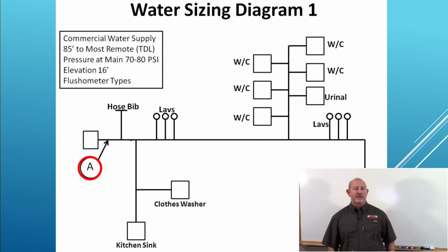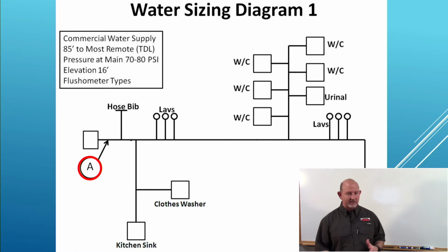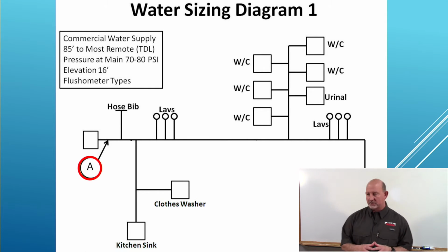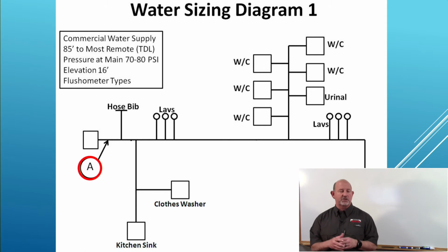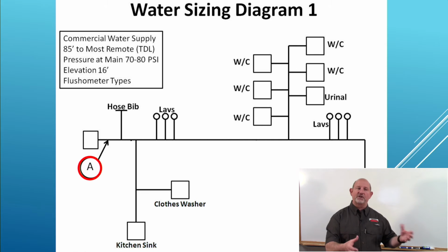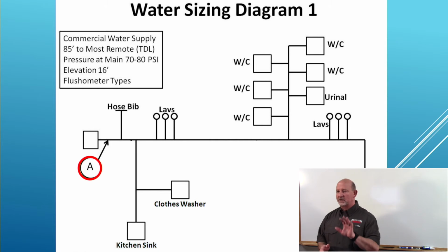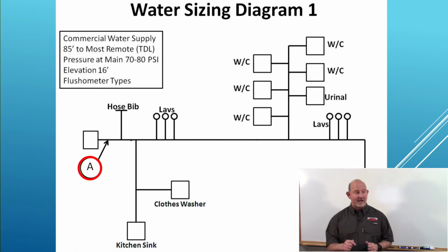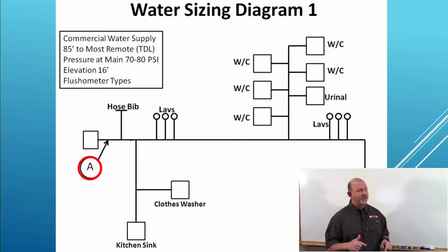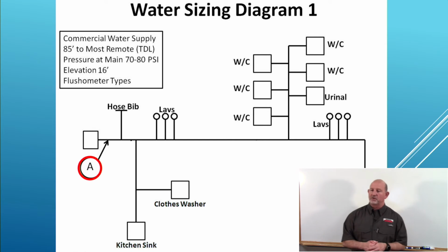And then the flushometer valve, right? These say flushometer type. These are actually flushometer valve fixture units, right? So the reason the code used to just say flushometer type, and then they added flushometer tank and flushometer valve, so we got to be more specific. So I'm telling you, these are flushometer valve water closets and flushometer valve urinals. So remember, if you're looking at that table on page 111, it's going to say refer to 610.10, right, to get the values for those.